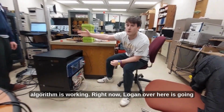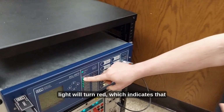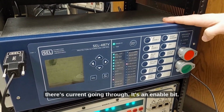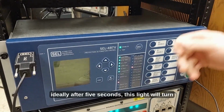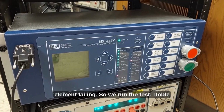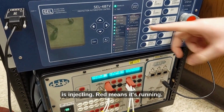Right now, Logan over here is going to run a test through the Doble test kit, which will simulate a capacitor element failure. This light will turn red, which indicates that our logic is working and that it sees that there's current going through. It's an enable bit. Then when we start running the test, ideally after 5 seconds, this light will turn red, meaning that our relay has identified a capacitor element failing. So we can run the test. Doble is injecting. Red means it's running.